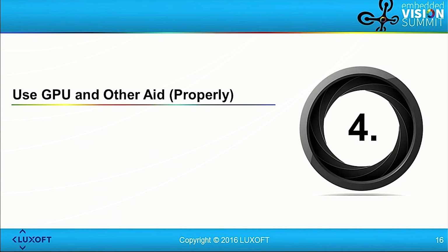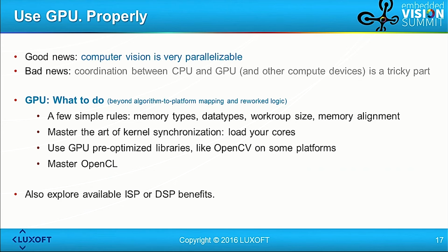One more important subject to cover is non-CPU architectures that are currently dominating or in some areas beginning to dominate the embedded world. There are some basic recommendations. The paradigm of programming is different. You need to care about memory alignment. You need to care about types, because as you benchmark, you will learn that these types behave very differently on these platforms.